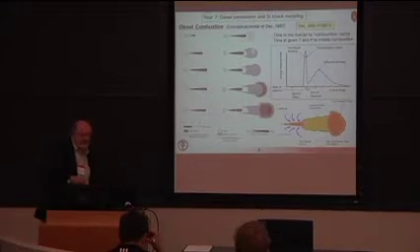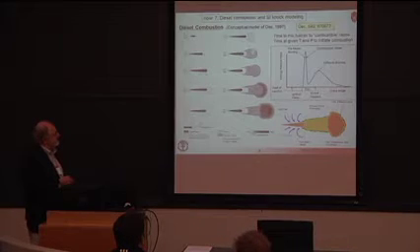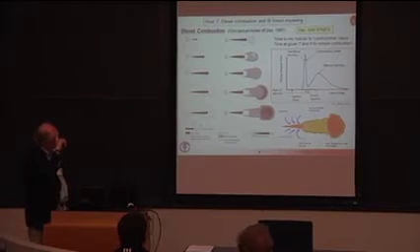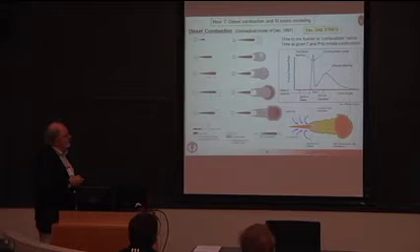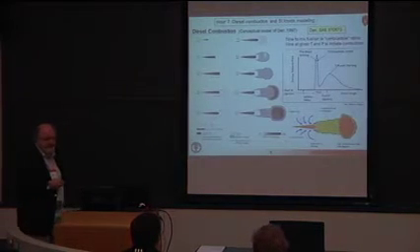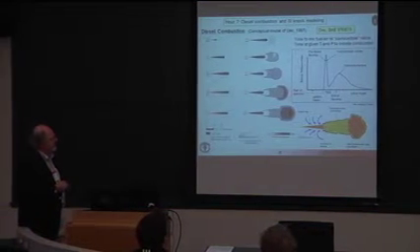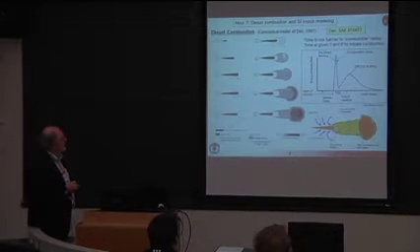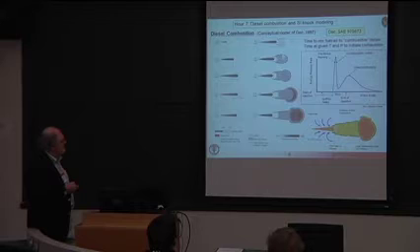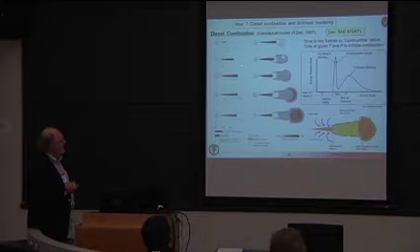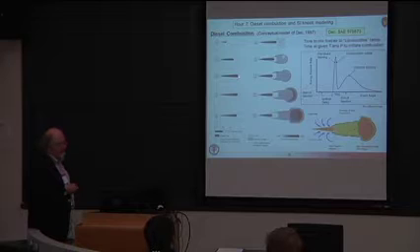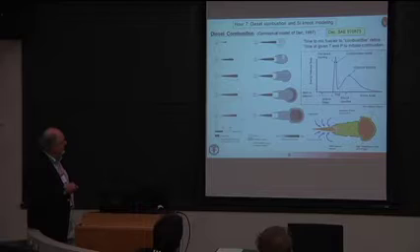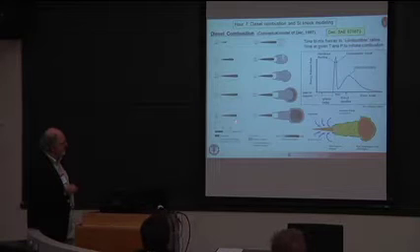So a lot of work has been done over the years, and at the Sandia National Labs, John Dec, some years ago, proposed a conceptual model of diesel spray combustion that changed the way people thought about diesels. So these are some images from one of his papers here that show the liquid fuel being injected, the liquid fuel penetrating into the combustion chamber from one of the spray plumes. And at a certain moment, the liquid length reaches its maximum, as we discussed last time.